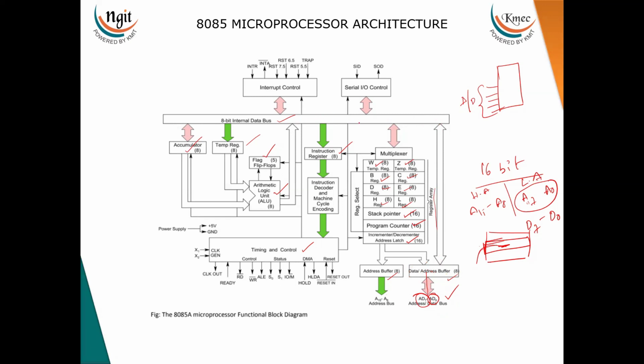And after that, if it is an opcode, it will be placed into the instruction register. If it is data, it may be placed into the temporary register, or into the accumulator or any one of the general purpose registers, depending upon the instruction we have given. Now this is about the